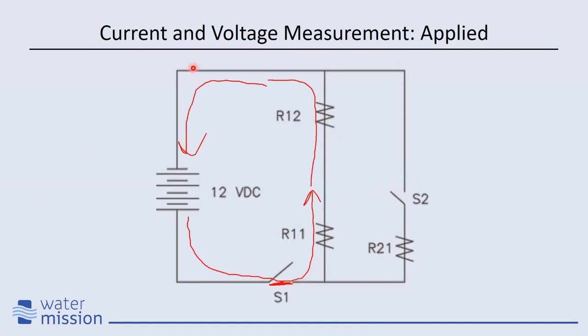Now let's say this switch is open now. That now means that current can no longer flow that direction. The only path the electricity has is going to be through this first branch right here, because we have two parallel branches, or two parallel strings, we could say. So electricity, if that's closed, can only go this way.